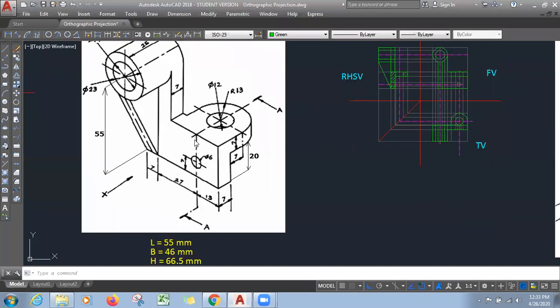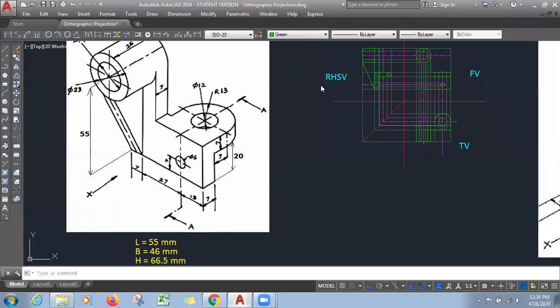So the cutting plane has to be given. Like here it was given, see this is the cutting plane, so cutting will happen at this place only, and in the direction of the arrow the object is to be retained, and the opposite part, this part, is to be removed. After removing that, the section that you will see will be your sectional view. So it is compulsory that they give the cutting plane.